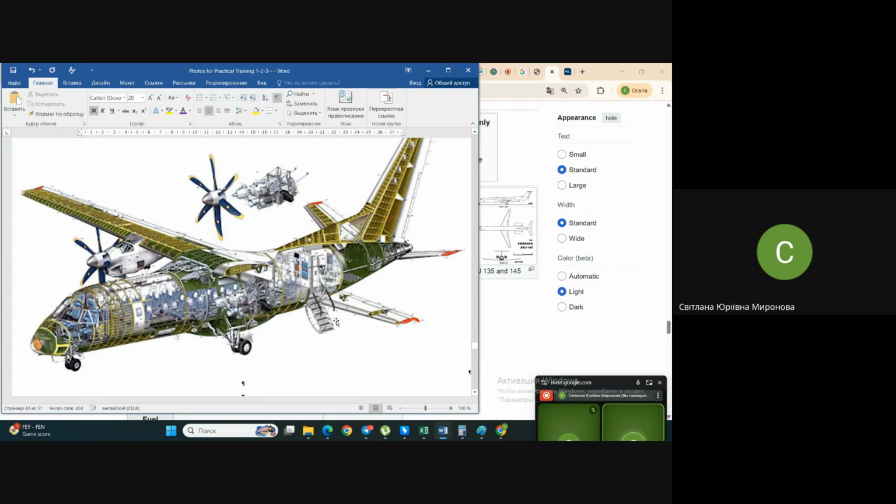Quite clear that this variant is possible when you have short landing gear, when you have engines far from the airfield due to using a high wing. You may not use additional airport devices for placing people on board and evacuating people from the airplane.